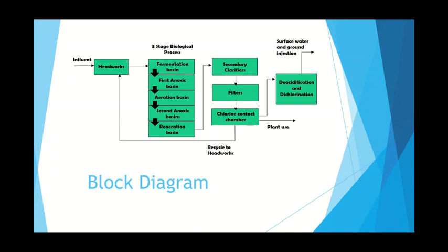The bacteria in the water goes through a period of stress. This is done by changing the environmental conditions. This makes them consume more phosphorus and nitrogen. Once this is done, the water is sent to secondary clarifiers to remove and collect the activated sludge.